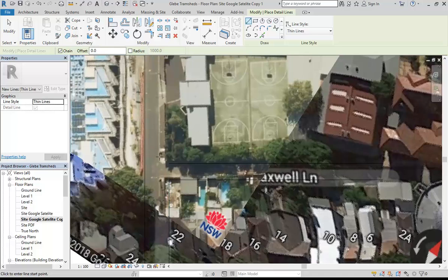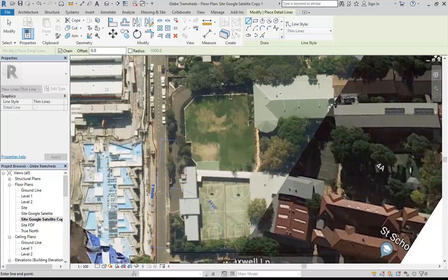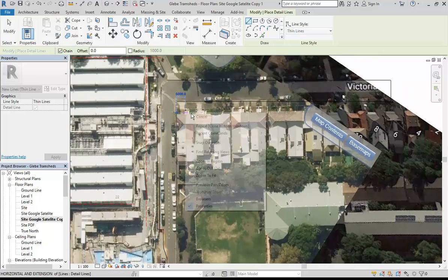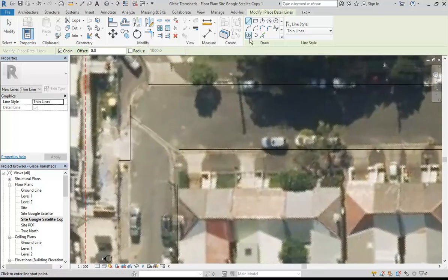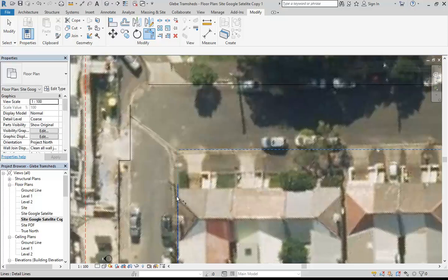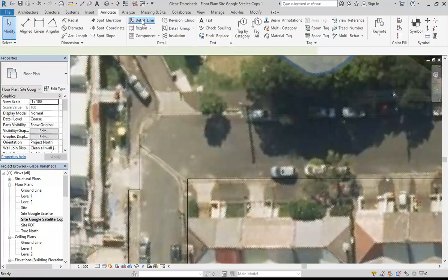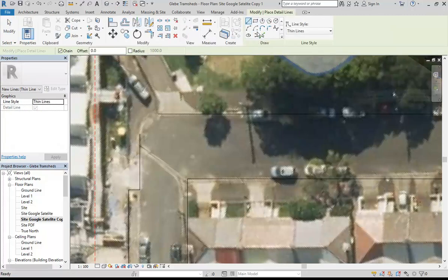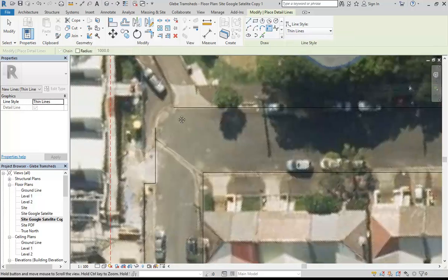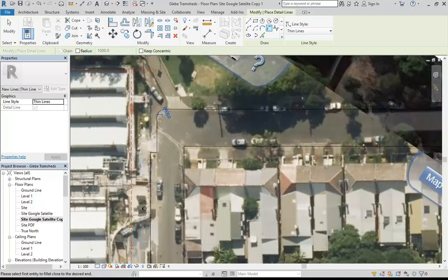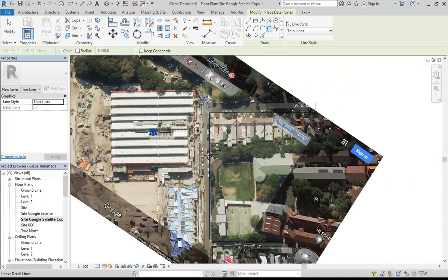If it's not clear, I'm going to use the sub-region tool to convert all of these into different surfaces in the end. But if I just went straight to drawing it with sub-regions, I wouldn't even be able to save it until I'd finished the whole thing. Here I can trim and edit these lines, and going back to detail line, we've got all these different shape drawing options, so make sure you're comfortable with those. We can use this one, fillet arc, if we need to put rounded corners between two lines. So all those quick drawing tools that you have, just for drawing quickly in 2D.